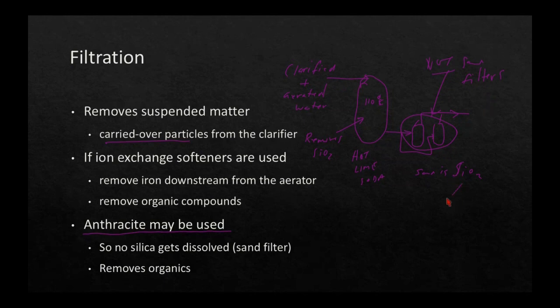Okay, and silica, if you're aware, last year you probably learned that it deposits on turbine blades. It makes a very hard scale inside of boilers. It's very hard to remove. So we really don't want to use silica sand filters.